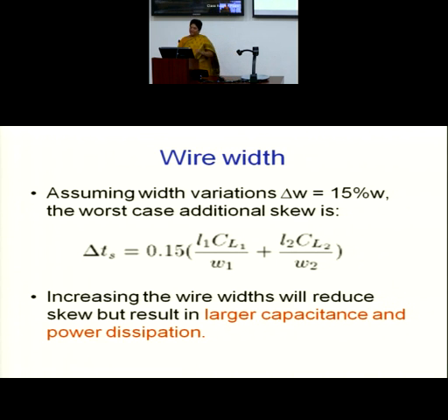So as I'm saying, I'm not looking at those noise issues currently. I'm looking only at transmitting my clock signal through a tree, and the design of a tree. My guiding parameter is the minimization of the skew between any two destinations. When I say minimize, I know what the permissible value is. I have to bring it below that. Ideally, the value is 0. So here I have taken the first decision that I would be keeping the wire segment width at a minimum value throughout the tree.